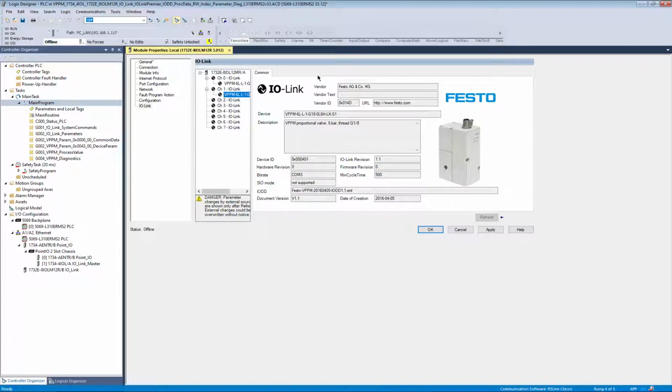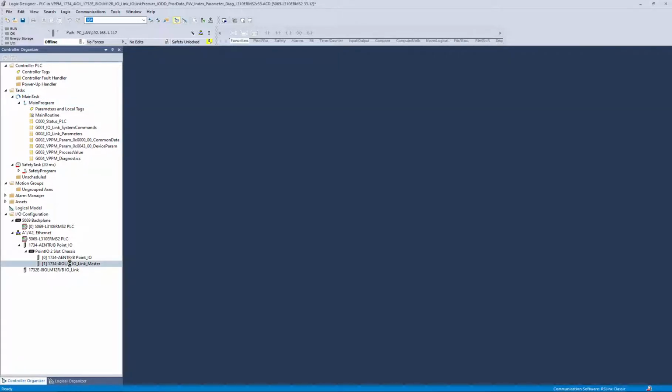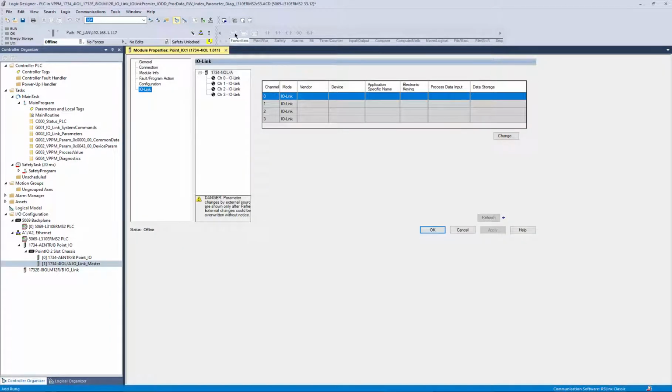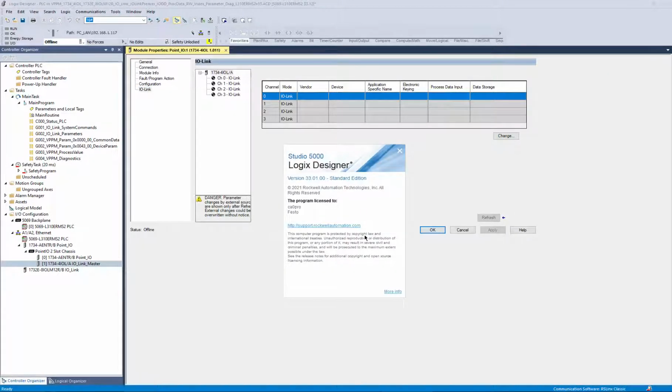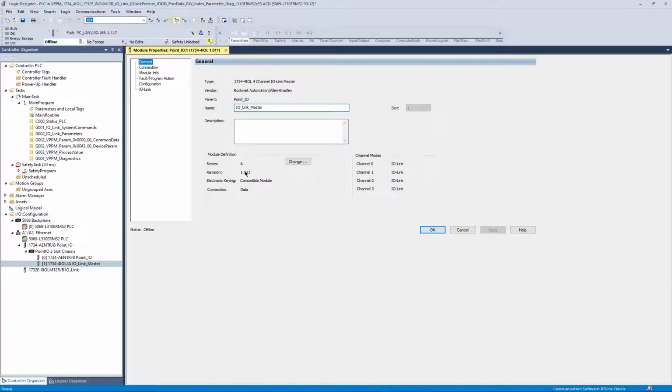Okay, this is a new feature with Rockwell, and it is how it is. If you have older firmware, I'm just going to show you this real quick. Let's look at this. Based on the version, I'm actually using a very new version, 33.01 Standard Edition. I've opened up the 4IOL here, which has the older firmware in it. If you look at the general tab, the version here has to match the firmware.